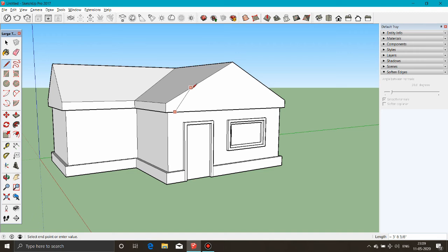Use the Line tool and start drawing a line from this edge. Now hover over the roof edge for a few moments, and as you continue to draw, you'll see a new inference that is purple in color and parallel to the edge we just hovered over. We can easily find out how far to draw this parallel edge by hovering over the ridge point to focus attention there. Then, as we come back to drawing our original line, SketchUp will tell us where these points meet.